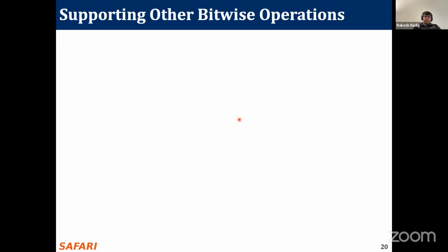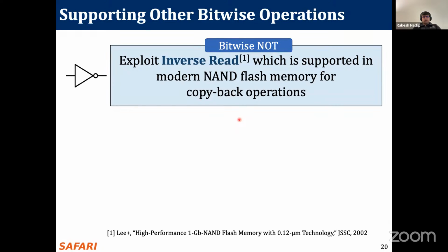So now we have looked at intra-block and inter-block operations, MWS operations, and we also support other bitwise operations in Flash Cosmos. So we support bitwise NOT by exploiting the inverse read operation, which is already supported in flash memory mainly for performing copyback operations.